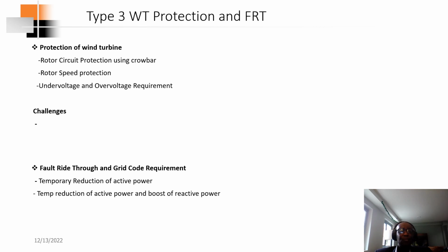have the deep and eventually continuous penetration of these wind turbines and inverter-based resources to the network, definitely there are a lot of challenges. One of the challenges has to do with protection schemes: inverter-based resources do not produce inertia to the grid or the AC power system network. As such, availability of the short circuit current required by protective relays is reduced. So it becomes very challenging to detect these faults.